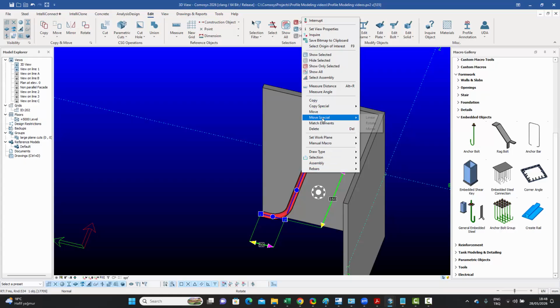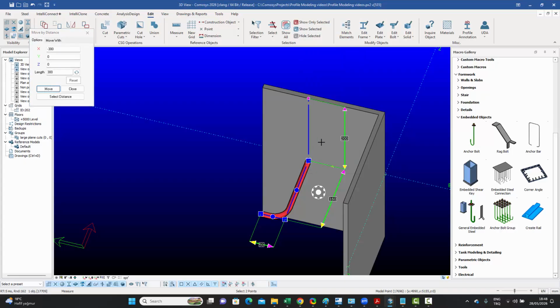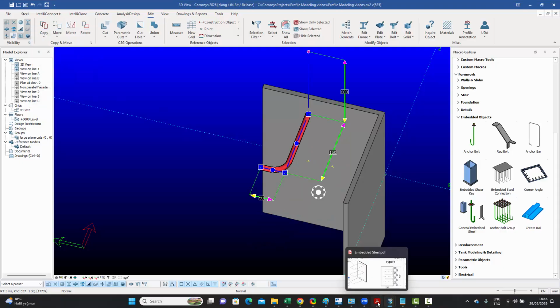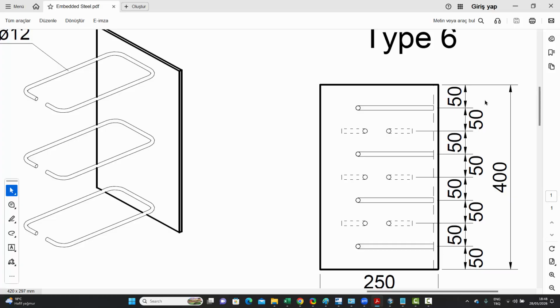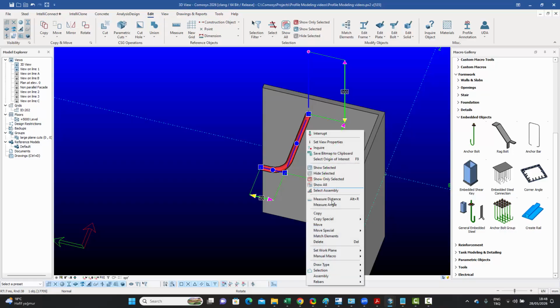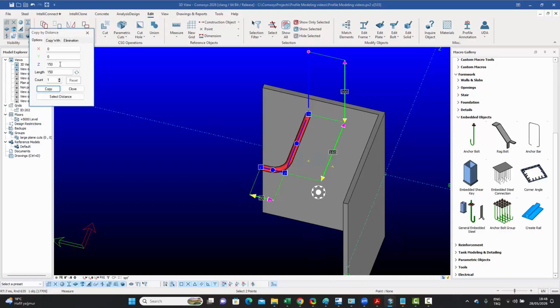So we can just select it and say move linear, and select this point, and then say that it goes to dz minus 50 from there. Just hover over that, so it's dz minus 50, like that. And then whatever z offset we get from the vector, we change the other one to 0, like that. And then we can just copy it down, I guess, 3 copies at a distance of 100 each. Say copy linear, this time in the minus 100, and 3 copies, like that.